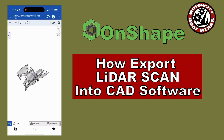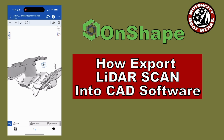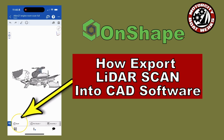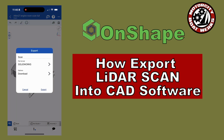There are online tutorials that explain how to use Onshape to clean up the scan or do different things. We're not really going to cover that right now. Now what you want to do is export this out into a format that can go into CAD. Go ahead and click on the bottom left tab. It says scan, and this should pull up this menu here. You want to choose export.